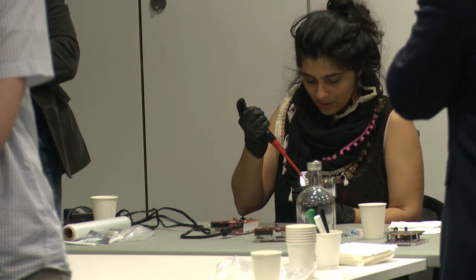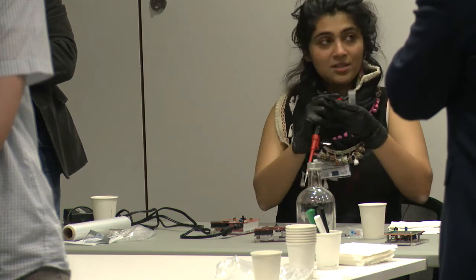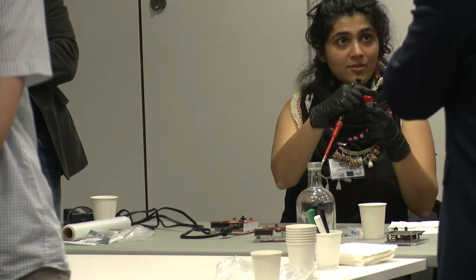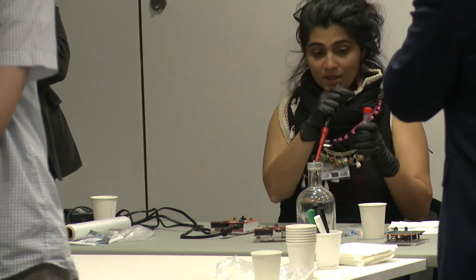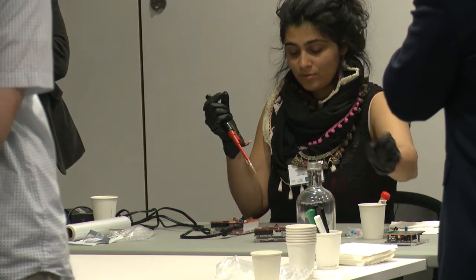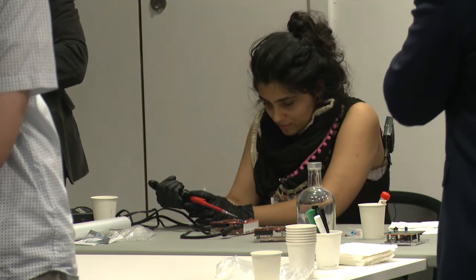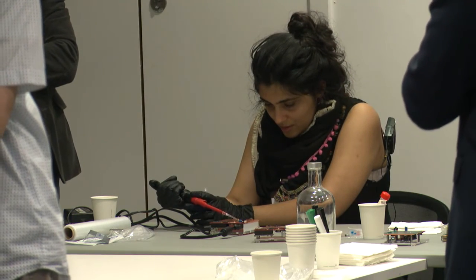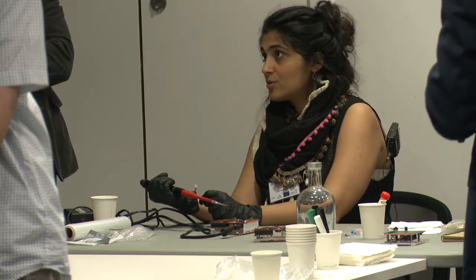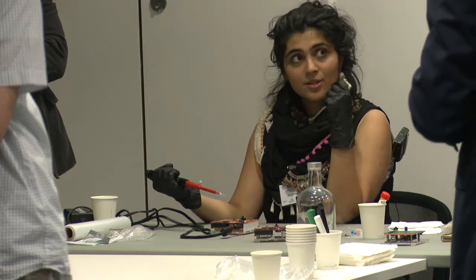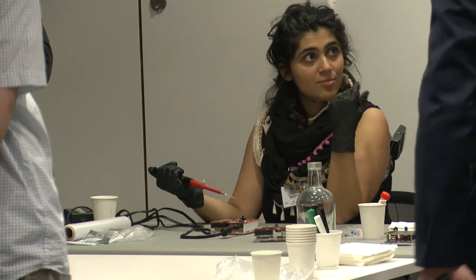That's the first thing. One reason could be that there are proteins bound to the surface, so again the coating is contaminated. Another reason could be that the electrode underneath has been overused, so it's deteriorated. Another reason could be that the dielectric layer is broken because of overusage. So the dielectric layer overcharges at some point and then it breaks down.